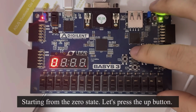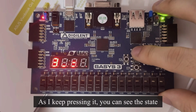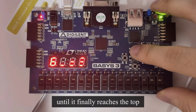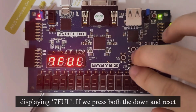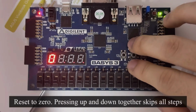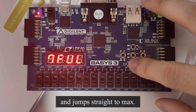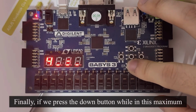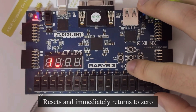Start from the 0 state. Let's press the up button. As I keep pressing it, you can see the state increasing step by step. The LED gauge fills up like stairs until it finally reaches the top, displaying 7 full. If we press both the down and reset buttons together, it instantly resets to 0. Pressing up and down together skips all steps and jumps straight to max. Finally, if we press the down button while in this maximum state, the system resets and immediately returns to 0.